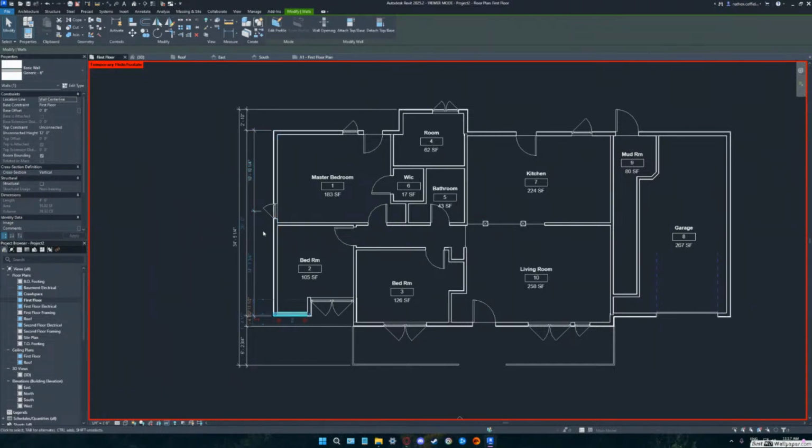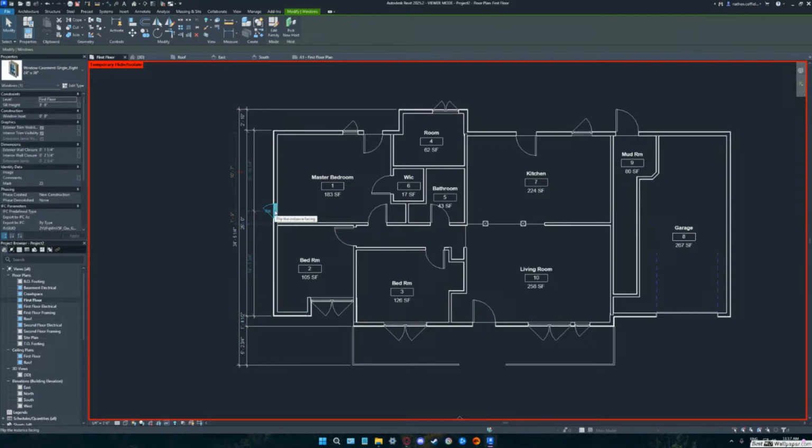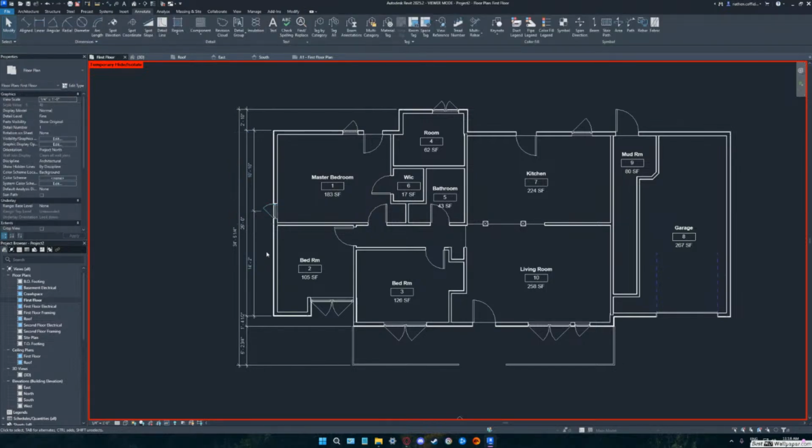Okay. So now what happens is when you go to the window that's in those bedrooms, you would find that if you moved it to 10 foot 10, you would end up with 2 clean dimensions. This one right here? Yeah. Instead of being 10 foot 10.25, you just make it 10 foot 10. Now you see how your dimensions start to clean themselves up. So you don't have all the fractions, and you work the fractions out of your job.